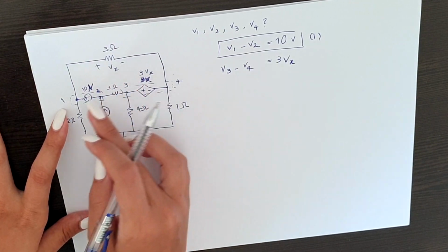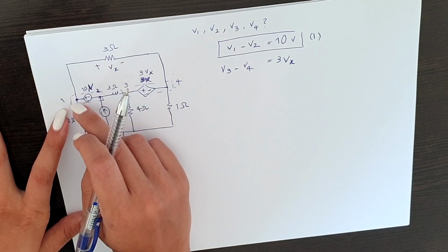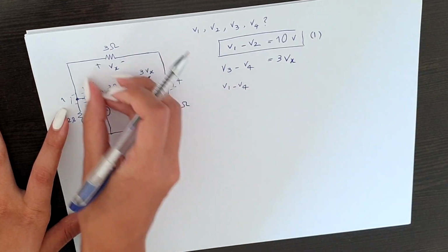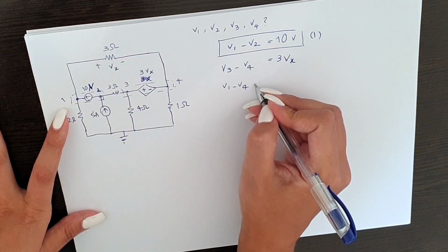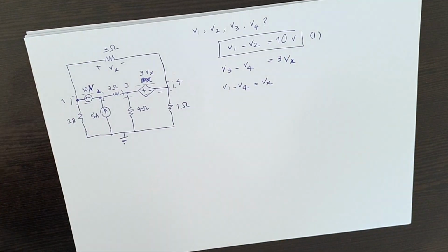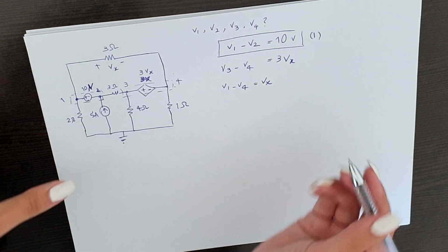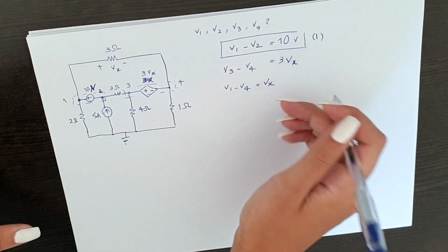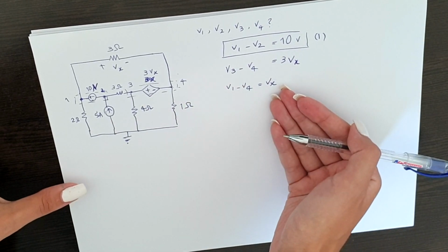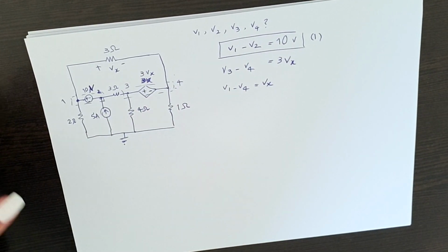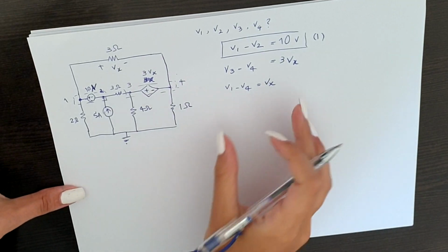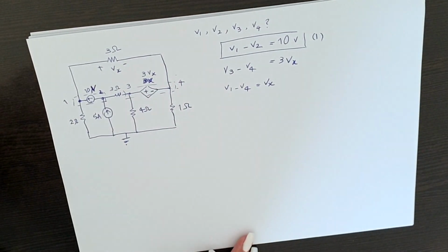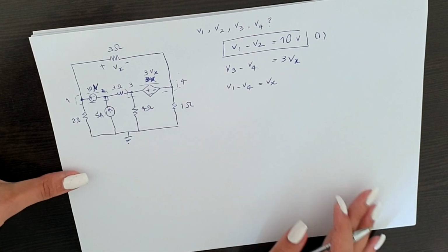but we know that our V in here is Vx. And we know that if we say the voltage from the positive side minus the voltage on the negative side, which is V1 minus V4, it's gonna be this voltage in between. So it's Vx. So how do we solve this? Now we can derive one equation out of these two. We need to omit Vx in order to just have V1, V4, V3, because we want to write an equation with these 4 different variables to have our second equation, and then we would need only 2 more equations.